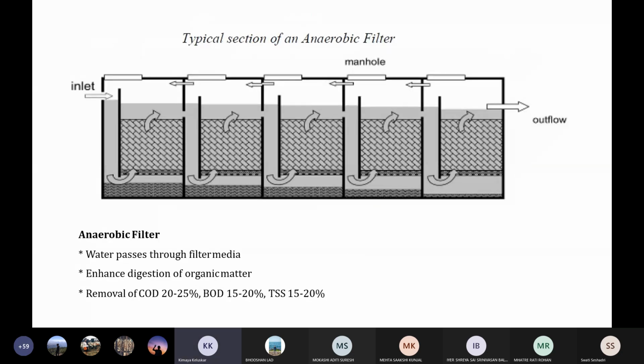These are similar. Now here, this is another settling tank which has filters in it. So the scum which gets on the top also travels to the next settling tank. The filter absorbs it and you get much clearer water. So even the minute particles are taken care of in this. So if you understand, the COD and BOD levels are now improved, and they are very important because they give you the health of the water. Next.